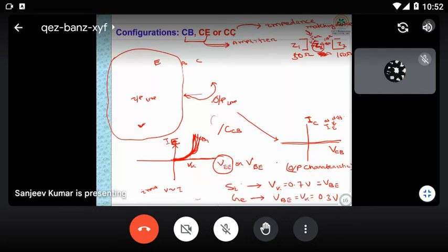But in this case, if I'm taking an example of 50 ohm and 100 ohm, different impedance levels, then whenever I'm sending or passing a signal, that signal may not reach the 100 ohm impedance level due to mismatch of impedance. So that's why we need another device or network which will give you a transition impedance level in between them.